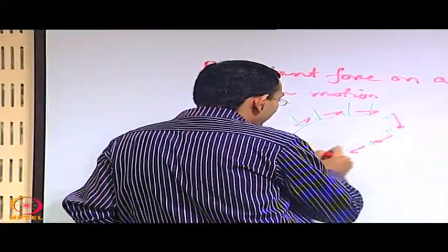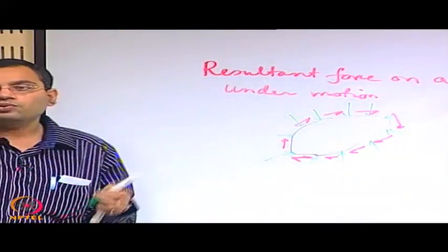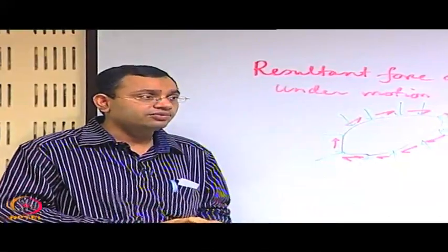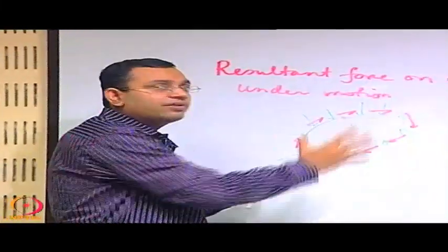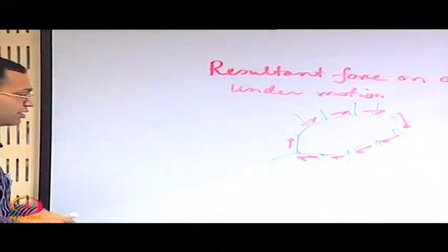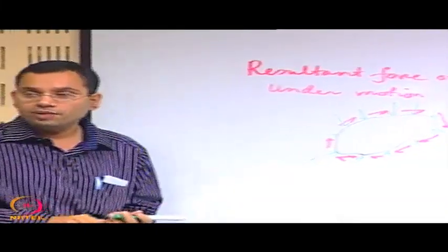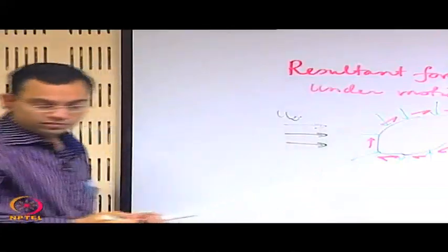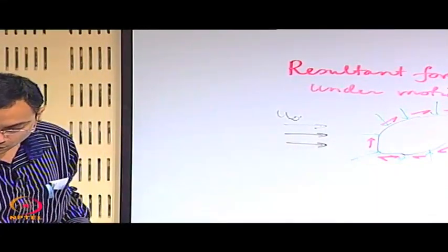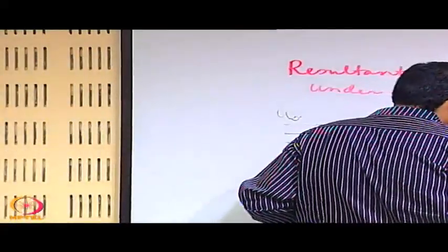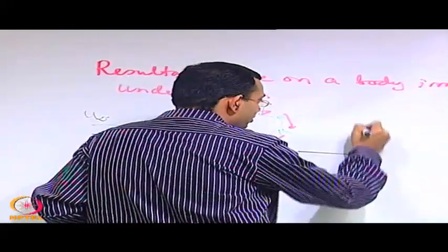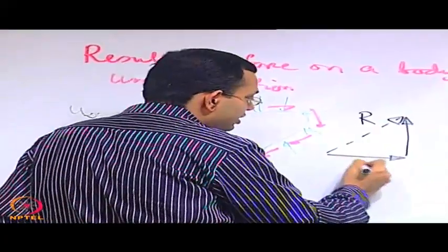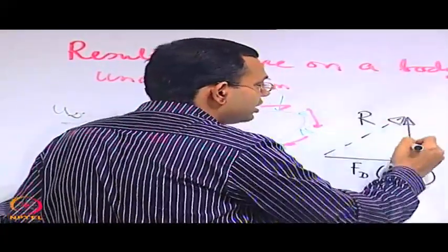So you can see that even mathematically whatever we considered as tangential forces and normal components of forces, those are automatically coming physically through the effect of pressure as the normal force and the effect of shear through the tangential force. The resultant force, if you integrate the net effect over the body, you may resolve it into two components. Of course you may resolve it into two components in many ways, but what is the important convention? Let us say that this is the free stream direction, the u infinity direction. So the force on the body is usually resolved into two components, one in the direction of the free stream and another perpendicular to the direction of the free stream, and let us say that this is the resultant force. So this force which is along the direction of the free stream is known as the drag force, and which is perpendicular to the direction of the free stream is known as the lift force.